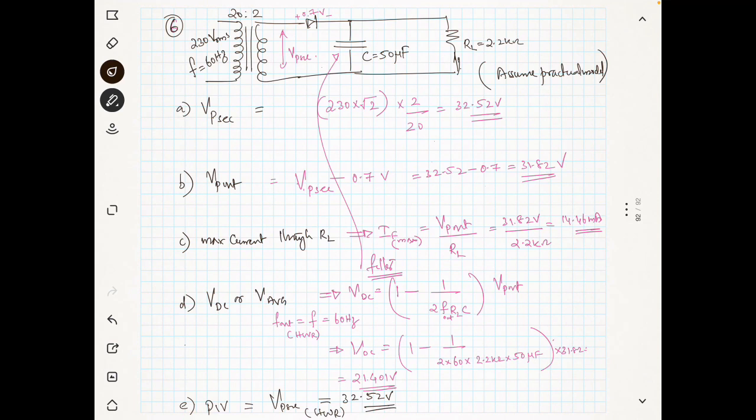Next we will see a circuit which is a voltage limiter circuit. So you have a voltage limiter circuit, something like this: there is a 1 kilo ohm resistor, and you have a diode and a battery which is given like this. This is 3 volt and this is your V in.